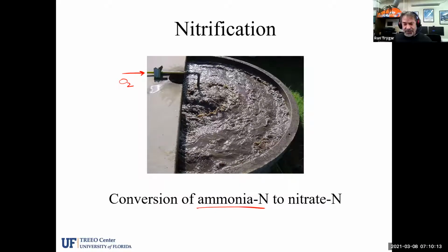One of the things that I have found over the years is that when we measure for this in a laboratory, or in our treatment plant process labs, our small plant labs, we generally have test kits that say that we're testing for ammonia. It's the easier form of nitrogen to be tested for with reagents, things like the Nessler's reagent and some of the other chemicals that we can add to a sample to cause a color change that we can measure with a colorimeter. So the ammonia becomes the form that's easier to measure rather than the ammonium.